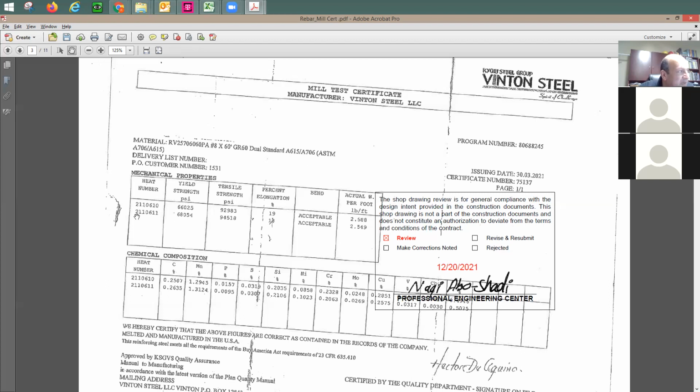So for example, this rebar is not working here for seismic. I cannot use this for seismic. And then the F ultimate is going to be 1.25 times this value, the yield. So for the seismic members, you need to work with controlled properties for the reinforcing bars, not for the concrete. Concrete is open, you can use any concrete. There is no minimum for the strength. But for the rebars, it's going to be kind of tricky here.